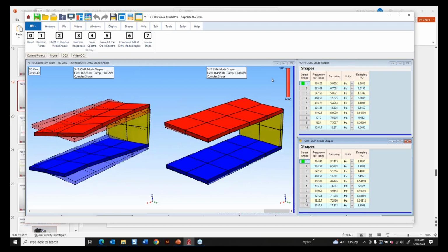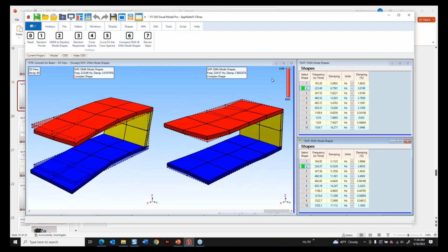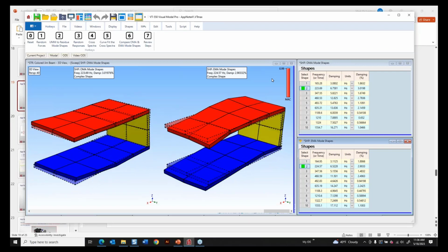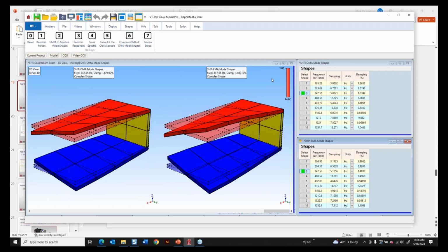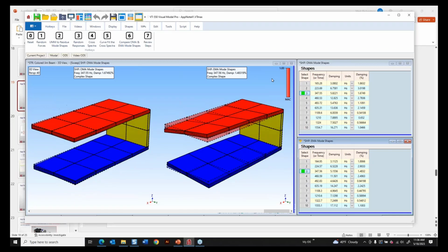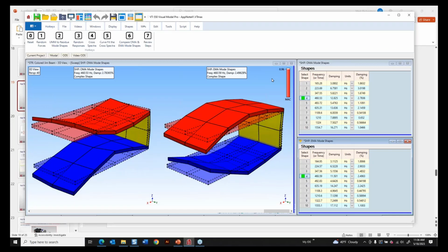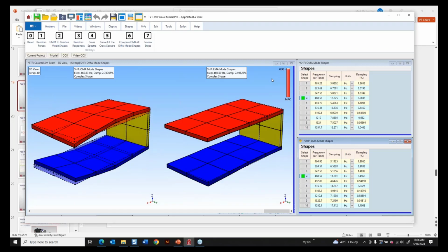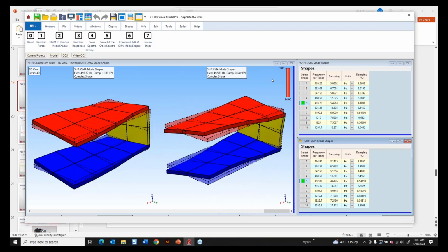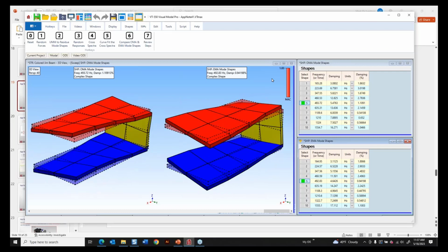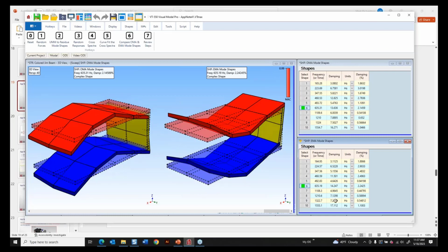MAC values always go between 0 and 1, so do the SDI values. MAC shows the collinearity, and SDI shows the actual difference in values. And again, these are complex valued, so complex arithmetic for vibration is what we use always.